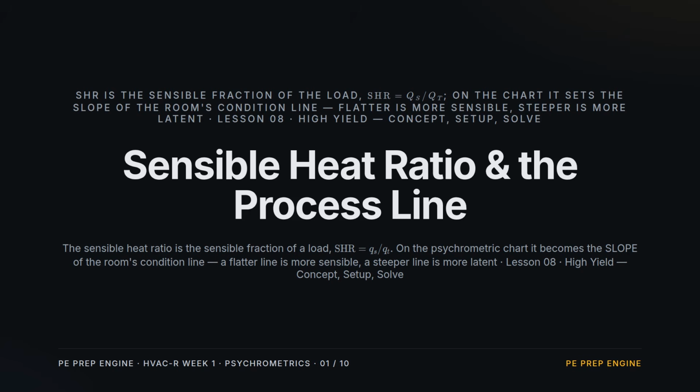Week 1, Lesson 8, Sensible Heat Ratio and the Process Line. The sensible heat ratio is just the sensible share of a load, sensible over total. But it does something visual too. It fixes the slope of the room's condition line on the chart. A flatter line means a mostly sensible load. A steeper one means more latent. We'll define it from the printed shortcuts, draw the line, split a real load, and size the supply airflow.